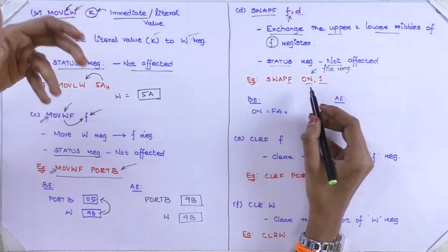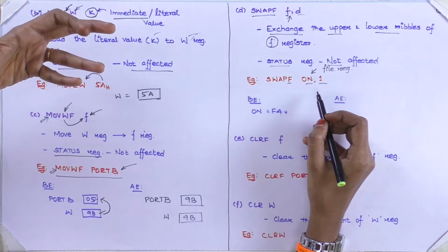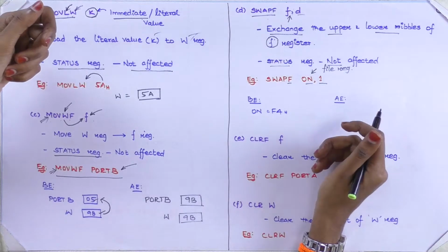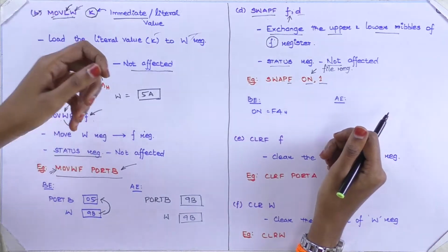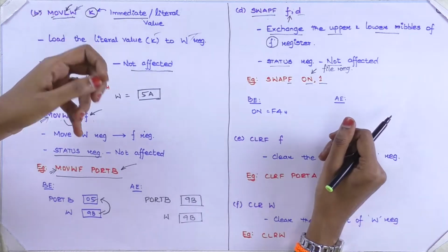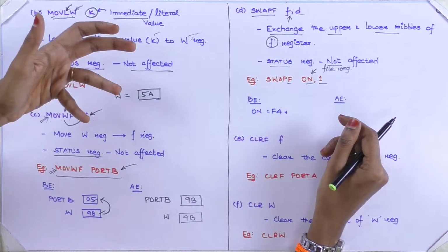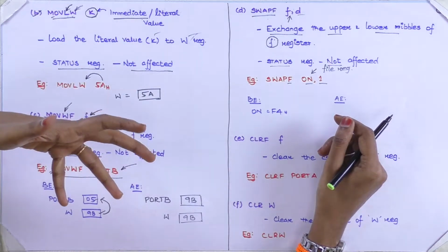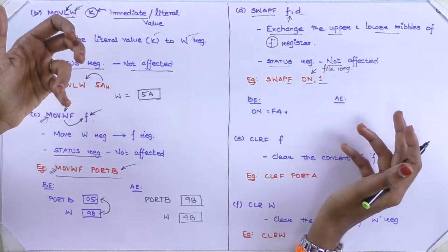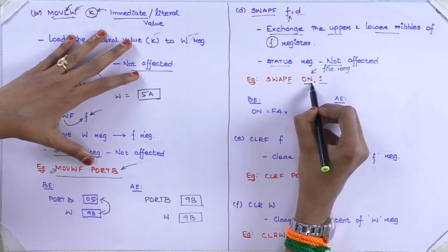So this depends upon the programmer; whatever name he wants to give to that particular register, he can give it, other than the names given to the special purpose registers. For example, if I say that in RAM memory I want to use the register at location 81H, I can use that register in the instruction as 81H, or else I can name that 81H as ONREG, or any other name that I wish to give. Now what I have to do is swap the value in the ONREG.